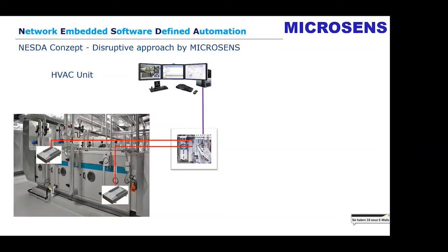You use the smart I/O controller, which I talked about before, to pick up local information like sensors, connectors or outputs, analog output to drive a valve. And inside this switch an application is downloaded, for example, which is doing the controlling of this ventilation unit.